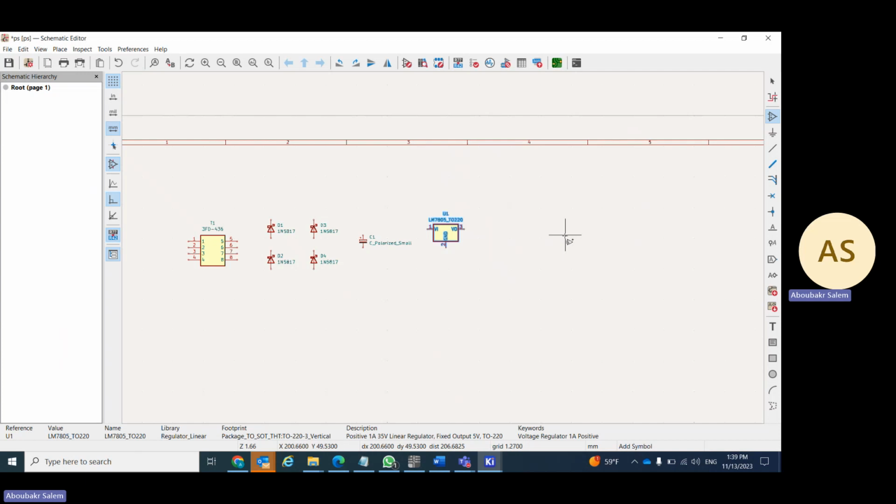So I'm going to duplicate this capacitor. We have capacitor one here. I will add it also after the regulator. This is one thing. Another thing is, if your power supply is going to supply some high frequency loads, like a microcontroller, for instance, you expect to have some high frequency ripples coming from the microcontroller. So we do prefer to have a filter for high frequency as well. A filter for high frequency means a capacitor in picofarad, not in microfarad.